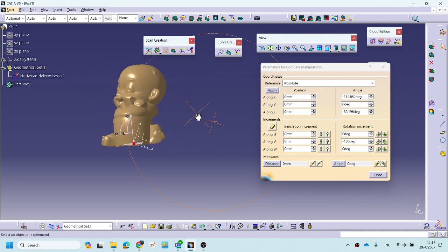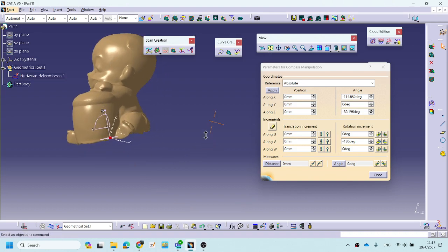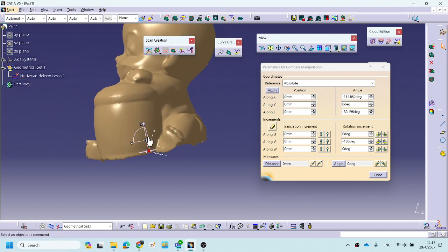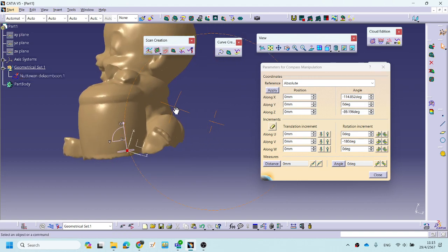And okay, still the orientation is missing. The orientation is standard, right? Okay, focus on x y z in the three axis system, the three axes of the absolute axis system, right? Okay, I just need to make the axis of the workpiece match and go along with the axis system, right? Okay, I fill in the zero angle, 0 degree angle, and 0 0 0 for x y z like this, and apply. Oh, I forgot to engage. Okay, 0 0.